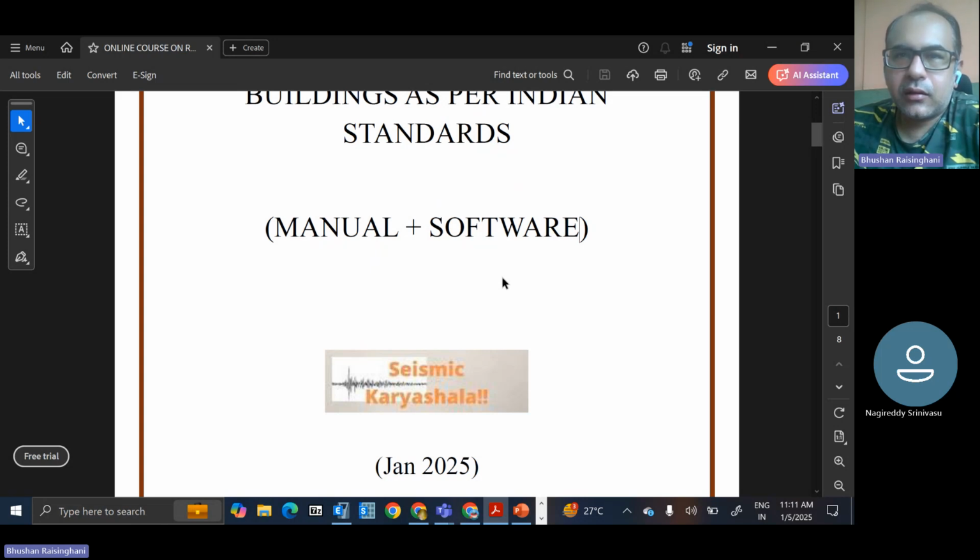Because eigenvalue solutions are with respect to the natural behavior of the building. That is what we say unforced vibration. Now, when we are going with the Ritz vector, only those modes which will get excited during the forced vibration, because the earthquake is a forced vibration. So, in the forced vibration condition, how many modes are going to be excited if we are doing analysis with respect to that? Right now, many people are going with Ritz vector for analysis in ETABS.